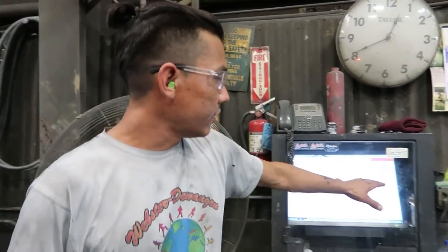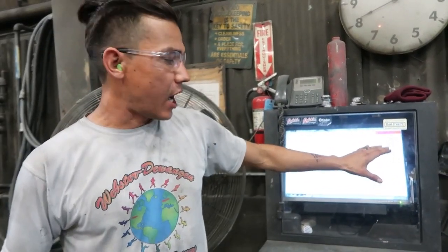And after we test our iron coming out of our cupola, we send it off to APL, Analytical Process Laboratories, and they send us back their results of the quality of the iron, and it's pretty much spot on. So everything that we do with the quality of our iron involves a lot of data, and we just make sure that it's being poured when it needs to, at the right time, because after a certain time the quality of the iron deteriorates.